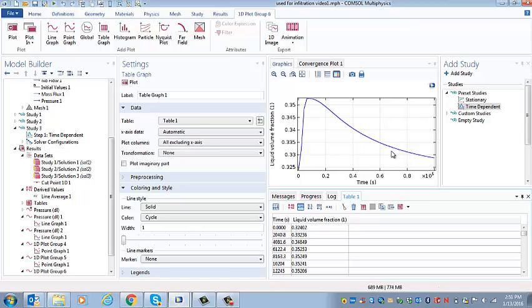And we might be able to do that, but something that we certainly could do would be to evaluate or measure the weight of the core as a function of time. We could do this with load cells. And so if we take the average water content, we can convert that into a load or a weight, and this curve here would be then a plot of the weight or the signal that we would expect to see in the load cell.